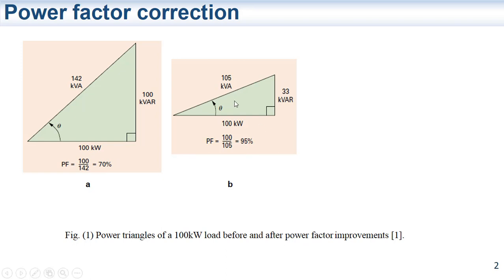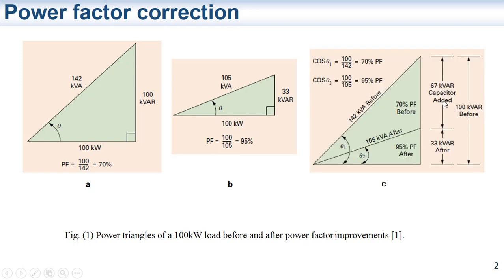Now this device or load is an inductive load. One way to reduce the reactive power is to introduce a capacitive load, or a simple capacitor. Therefore the total reactive power will be reduced, which means an improvement in the power factor. This process may be referred to as power factor correction.